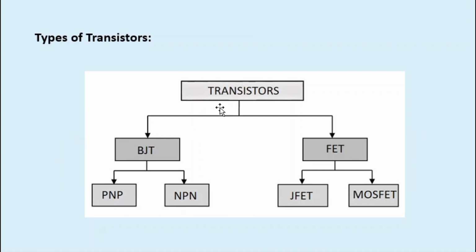There are many types of transistors, and each transistor specializes in its application. But the main classification of transistors is as bipolar junction transistor, known as BJT, and field effect transistor, known as FET. Bipolar junction transistor. A bipolar junction transistor, shortly termed as BJT, is a current-controlled device that consists of 2 PN junctions for its function. It is configured in two ways as NPN and PNP. Among the two, NPN transistor is the most preferred for the sake of convenience.